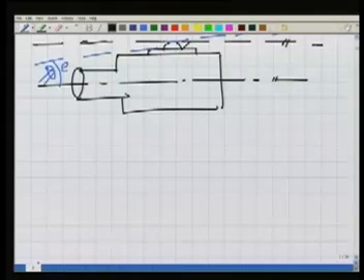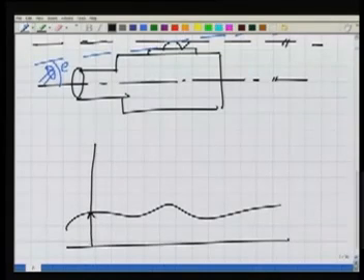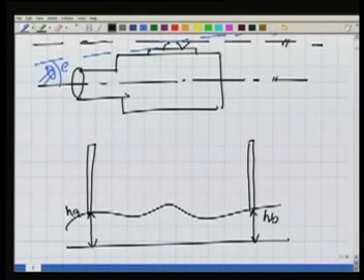Let's draw the datum, this is the terrain, and over here I know, let us say, HA, and my desire is to determine HB. I am keeping my staff at this point and at this point. My level is kept somewhere here.